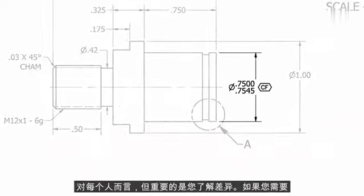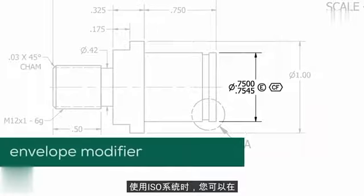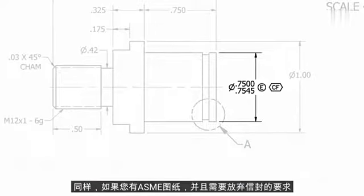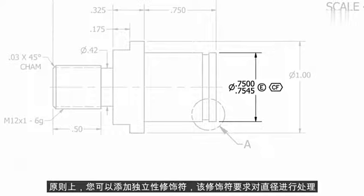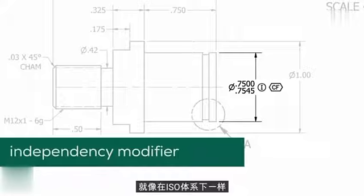If you need the envelope principle when using the ISO system, you can add the envelope modifier after the tolerance, which makes the interpretation equivalent to the ASME system. Likewise, if you have an ASME drawing and you need to forego the requirements of the envelope principle, you can add the independency modifier, which calls for the diameter to be treated as it would be under the ISO system.